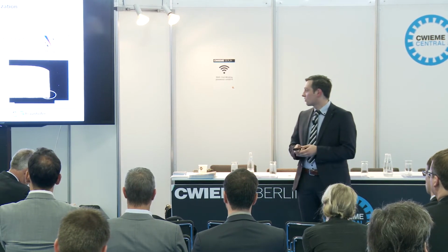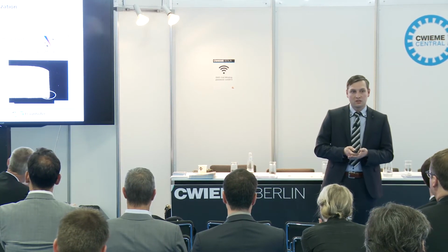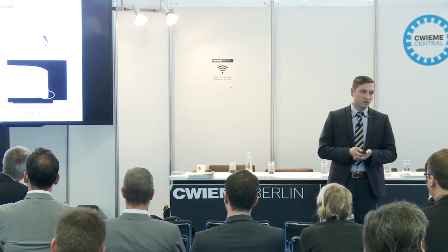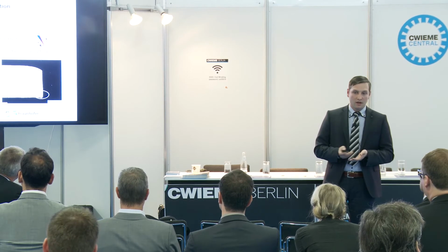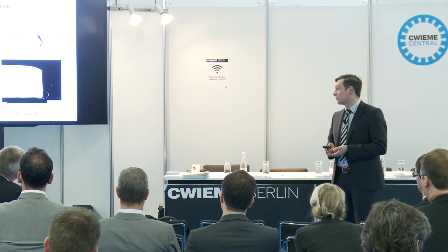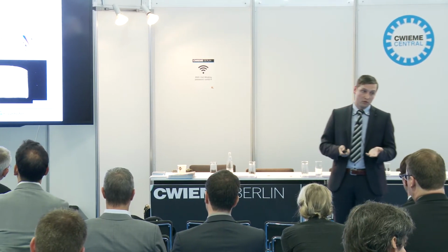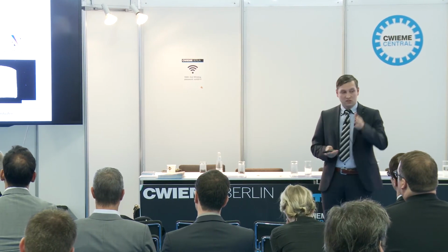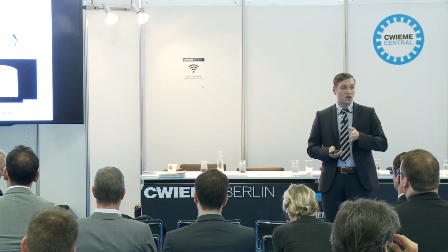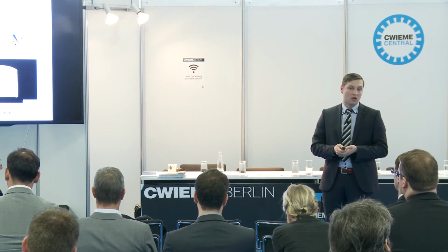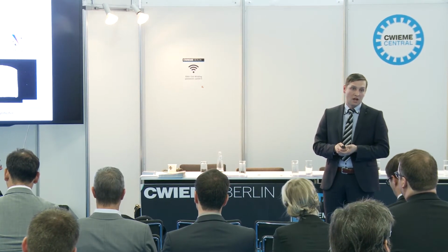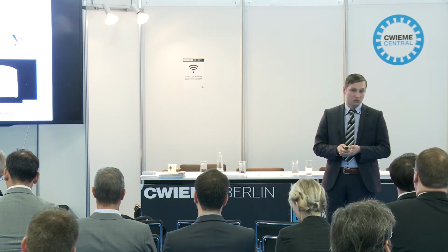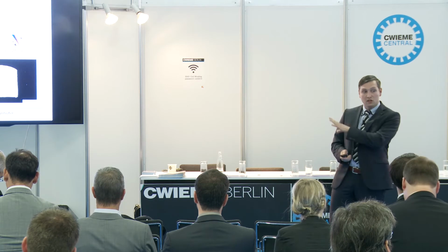Mechanical cutting causes this burr at the back side of the lamination. There is no burr for laser remote cutting due to the burr removal. But if you process thicker materials, we see a slight wavy shape of the cutting edge. For thinner materials like 0.35 millimeters or NO20, NO10, that is not an issue.